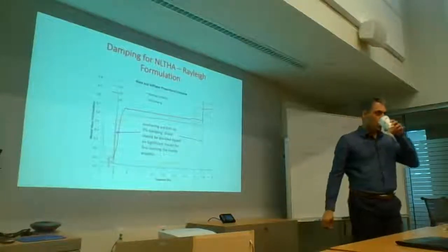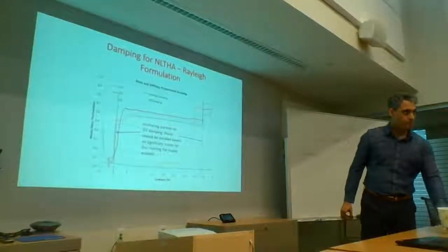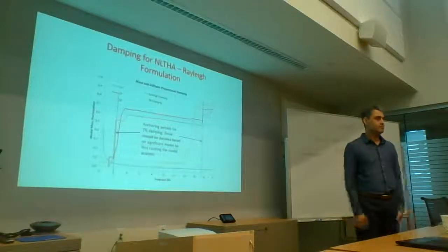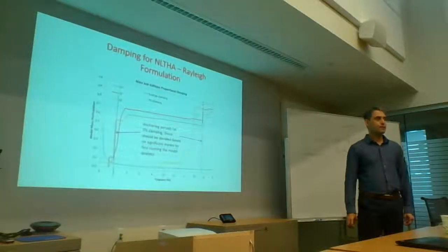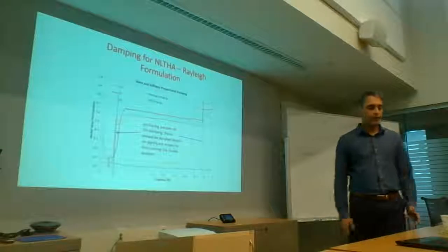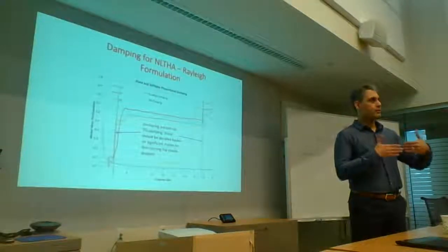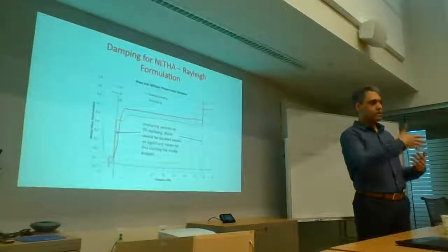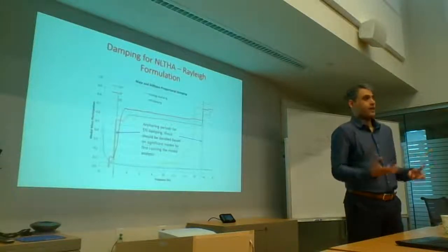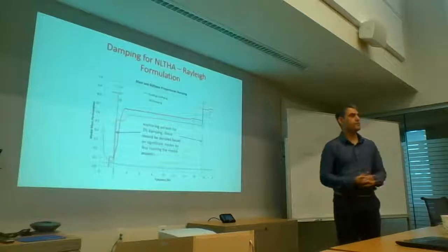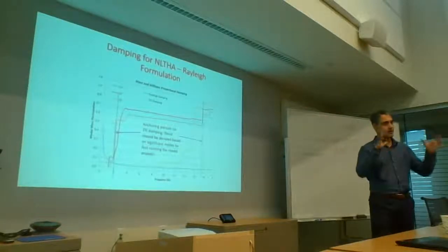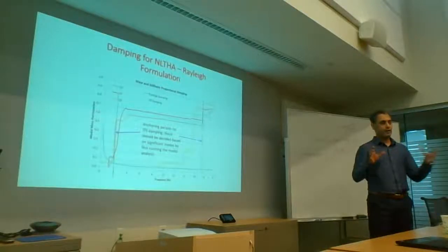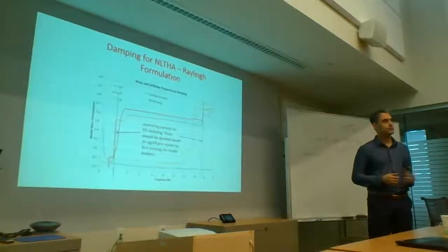What if they were very much different? Then that's a shortcoming for this model. Check and see how much the vertical matters. Then you'd have to maybe run it twice, one with a damping that's targeting the vertical, and see if it's in fact giving you a lot of effect. So then you're in that gray zone of, okay, now my engineering judgment is going to kick in. I'm going to do different analyses and try and bound it. Okay?